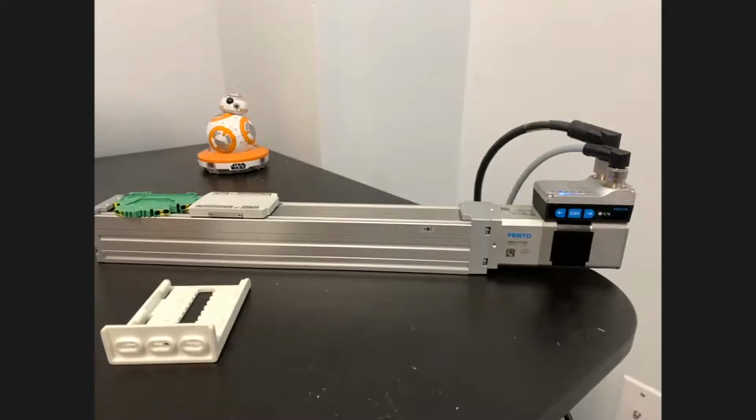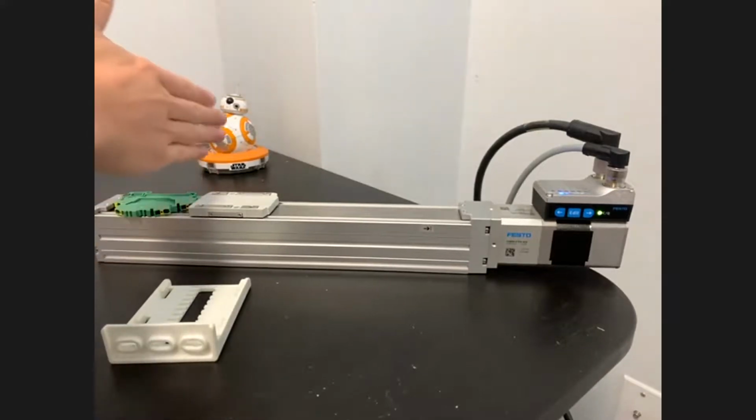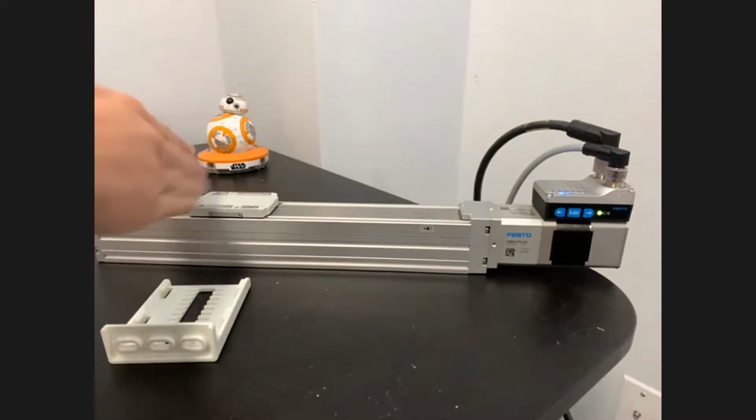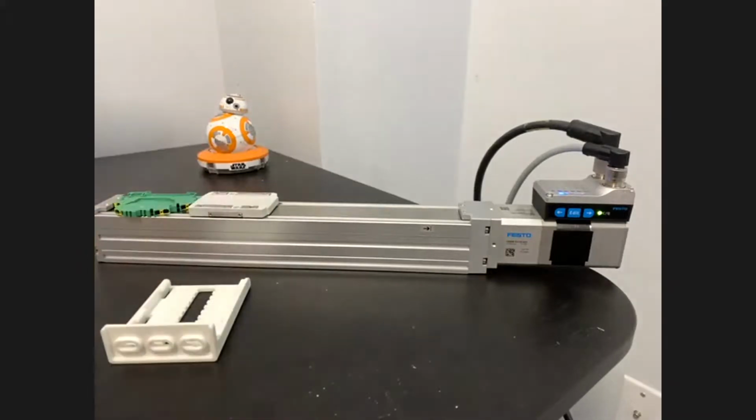Now it's actually looking for a force limit. And what we can do is set the force limit in 10% increments of the total force. So 10, 20, 30, 40, 50% of the total force. That's nice. Here it's searching for the part, and once it hits the part and reaches, in this case, 50% of the total force, it says, all right, my motion is now complete. And then from there, we do a read of the current position, and we know where the part was when we hit it.